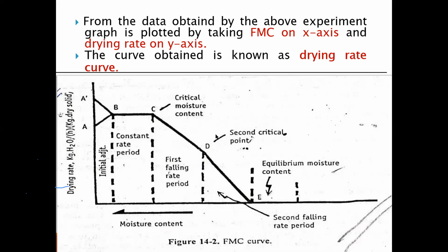If the moisture inside the solids does not come to the outside surface, what will happen? There is a time gap in between, and that is called a dry spot. In this case, the material will not be dry. The time gap in the diffusion of water from the inside solids to the upper surface means a continuous film does not form on the surface.